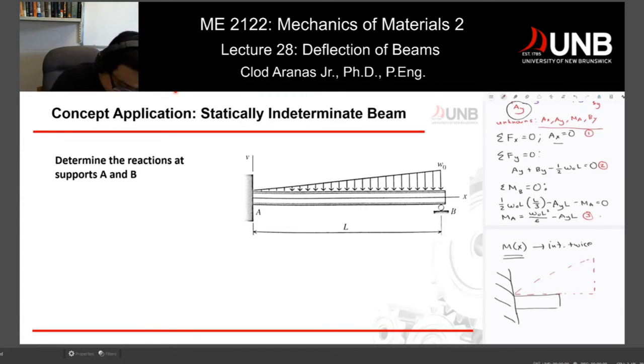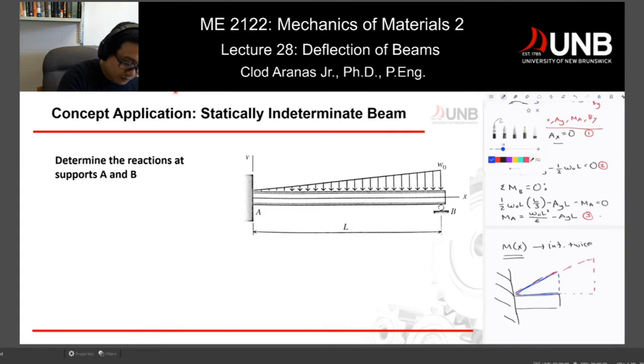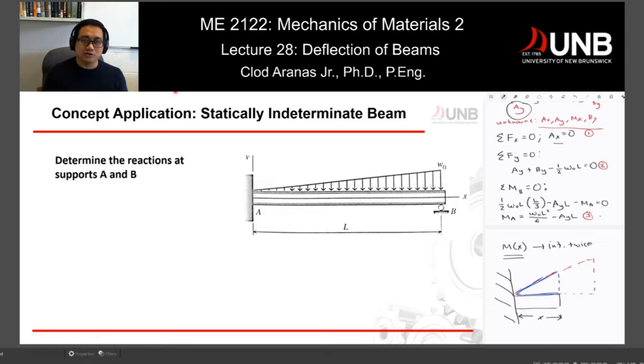So that's the original size of my triangle. I will not write the arrows right now, but just assume that's your distributed load. And I cut the beam somewhere in between A and B. And if I cut my beam, I would get this blue thing right here, the blue triangle. And note again, that's a distributed load. I just didn't put the arrows, but everything is going down. Now, what do you know so far when you cut that beam? Now, when we cut a beam, it has a certain length, x. x is anything between A and B.